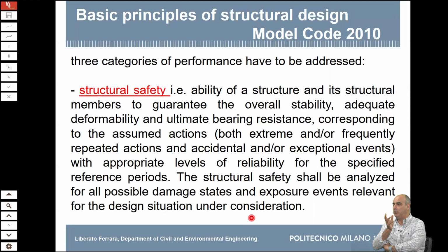We have to guarantee sometimes also what we can understand as deformability. It's written there, but you may claim, well, you have just said that the deformation of a structure is a serviceability limit state. Well, yes, it is. The cracking can be a serviceability limit state. But think that you have a water reservoir, which is excessively cracked. And if the crack is passing through, your water reservoir does not contain the water anymore. It's leaking. So that is an ultimate limit state, which means that you cannot any longer use the structure.